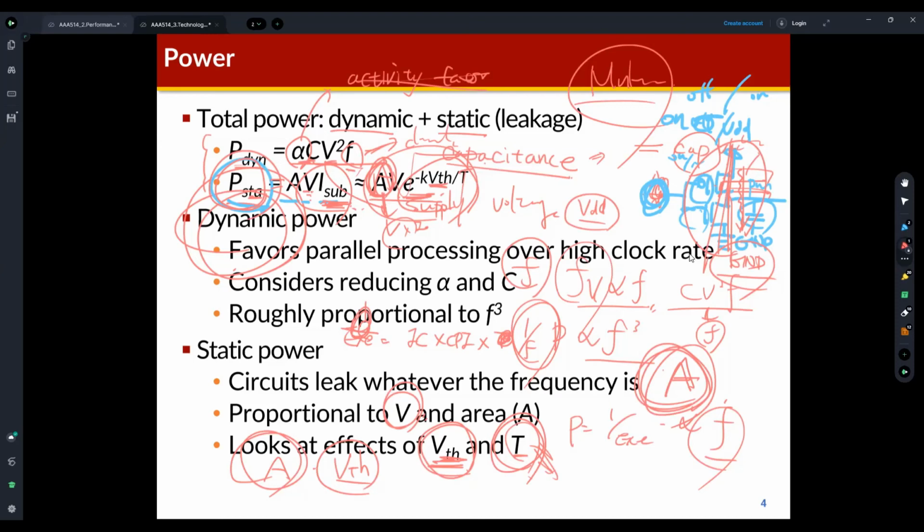Oh, it's good. But we are living in the multi-core era. We prefer multi-core architectures because they are very good for performance and for recent applications. So it's a good solution, but we need to include more transistors in our processor chip. How can we handle this static power? That's why the static power is a very critical issue in recent processor chip design.